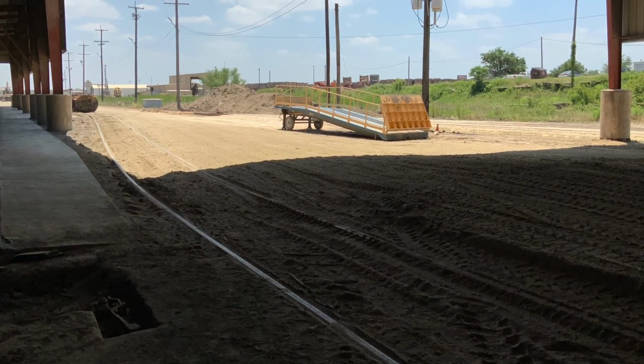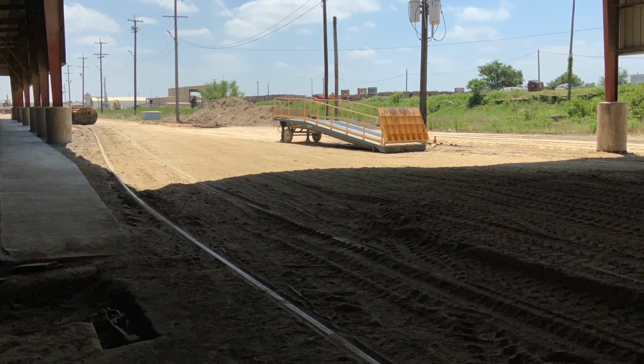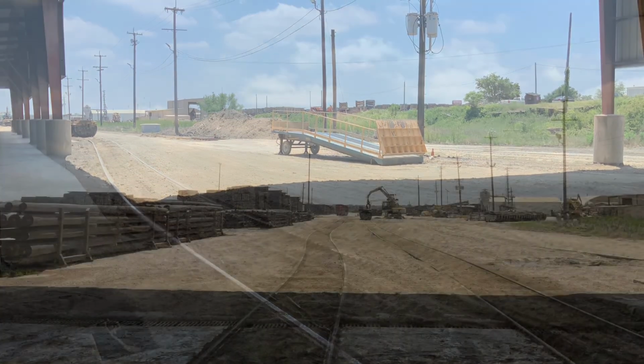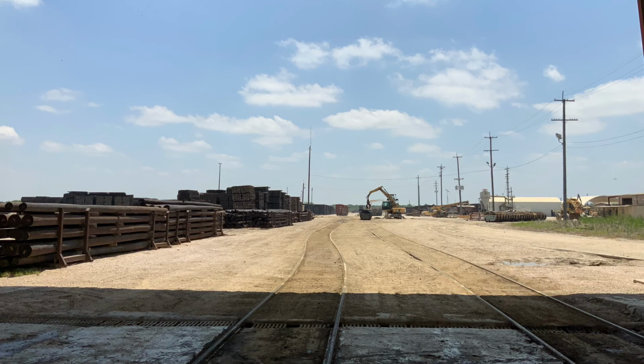Drip pad slopes and containment should be continually monitored. Vehicle entrance and exit areas can be subject to a buildup of soil. Soil mounds surrounding the drip pad should be kept lower than the level of the containment berm to prevent potential runoff during a storm.